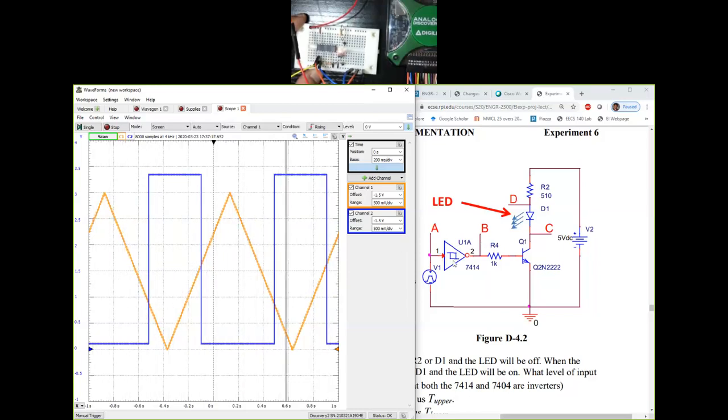And it was a Schmitt trigger based inverter, so we expected this to have two thresholds. And as you can see, it switches from low to high at a much smaller voltage when you compare it with the input voltage that is needed to switch the output from high to low.